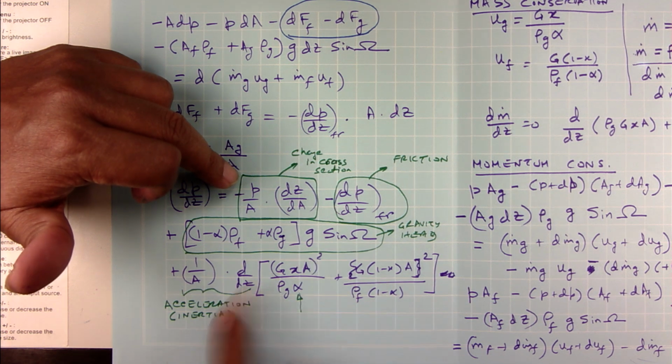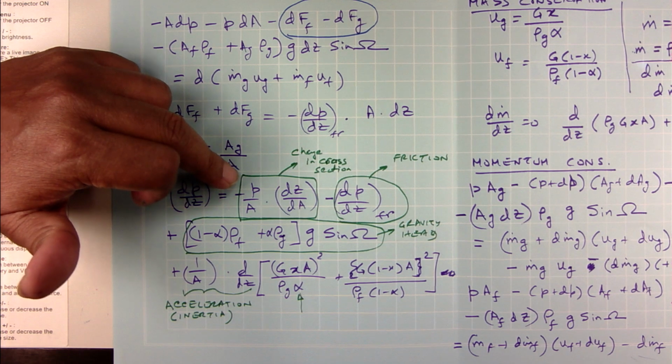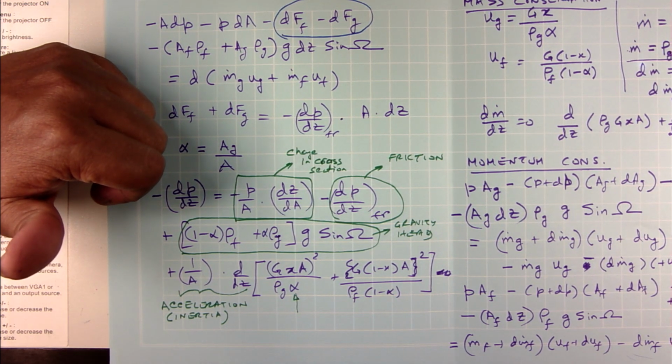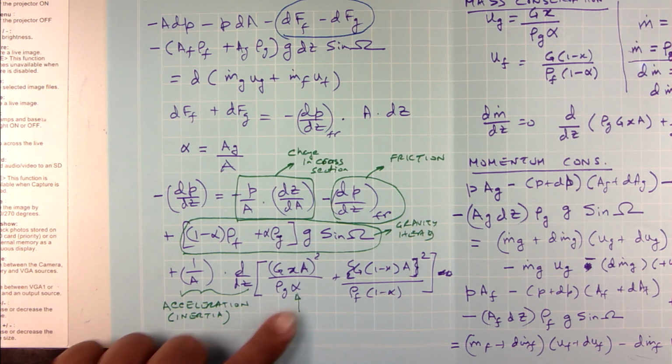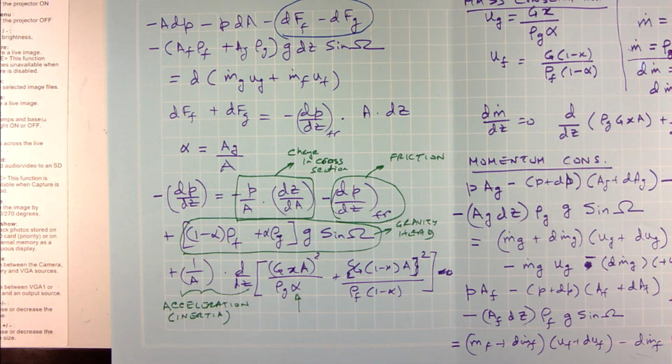Okay. So at the end of the day, as a thermal designer, as a thermal fluidics engineer, what are the things I care about? I care about what is the pressure drop for a given flow rate or mass flow rate. And then the other thing I care about is how much is my heat transfer. And then what complicates the situation is this thing called void fraction, and if you look in the literature, there are a lot of people who have given a lot of correlations for void fraction. So we will select a few of them, but at the end of the day, what really matters is these correlations will become a function of your